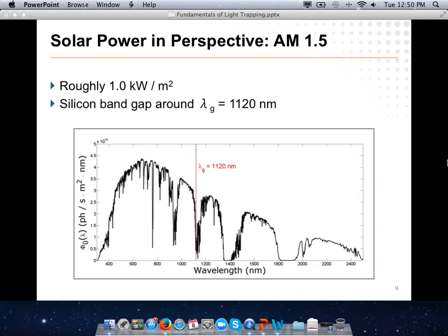If you go to NREL's website, they have these databases of solar references. So there's the AM0, AM 1.0, and then AM 1.5. AM0 would be imagining yourself sitting in a satellite and looking at the sun and asking yourself, what's the average daily energy I receive from the sun without any atmosphere to get in the way? Does that make sense?